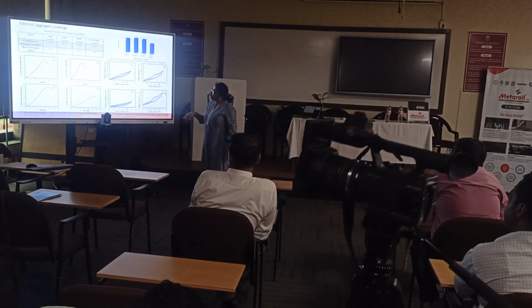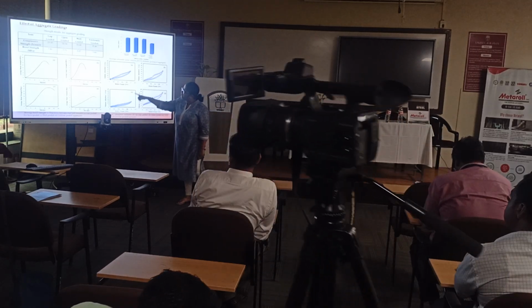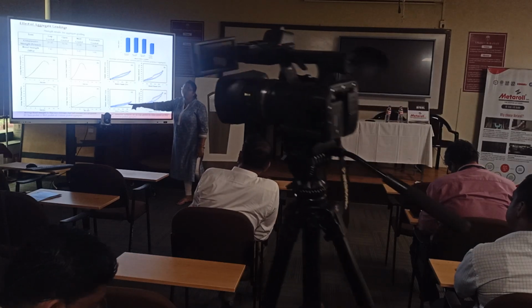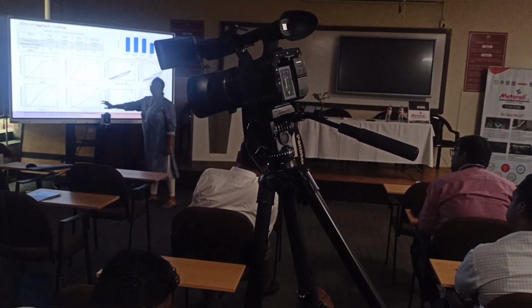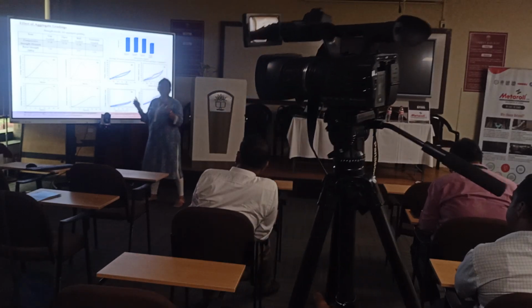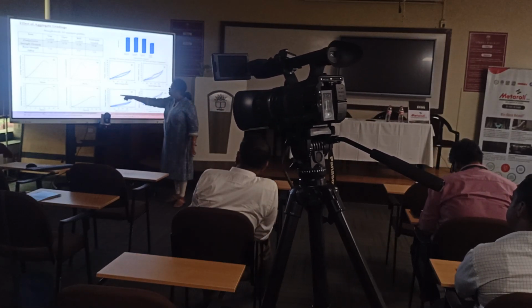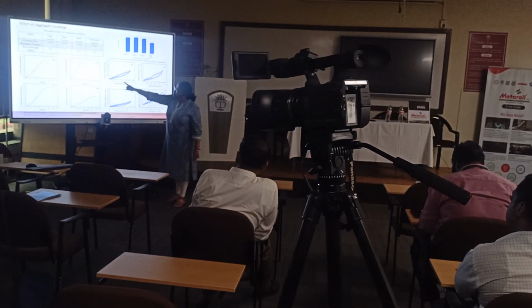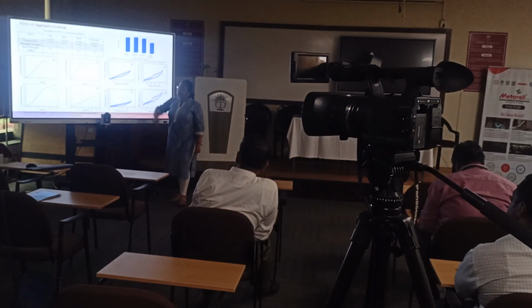And which one has more elastic effect? All three have elastic effect, but the slip is maximum for single graded, because the larger the mortar content, the more elastic behavior. A single size aggregate has more mortar, so you have a larger elastic behavior. But for the open, well graded and gap graded, the behavior is similar, and having the same system, it doesn't have much impact. So let me show you the final one.